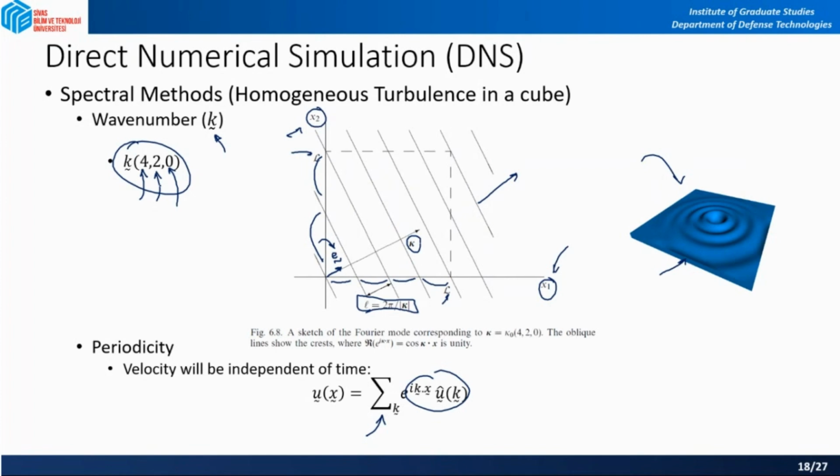So the first thing that I can do to simplify is to assume periodicity, repeating, meaning that I'm hoping that the collection of all these functions will represent a real flow field, so I can implement periodic boundary conditions on all faces of that cube. I just talked about it, such that, for example, if there is a cosine wave, it will repeat itself after the domain.